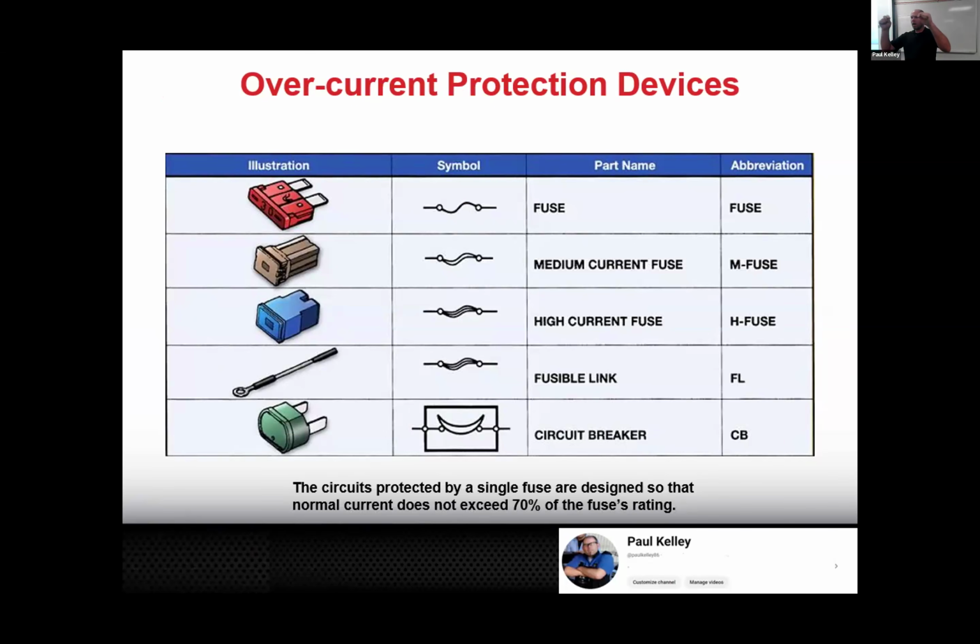You'll have regular wire, and then when they need to put a fuse in, but there's no room or something, they'll just cut a section of the wire out, and they'll put in a smaller size wire with a very gummy insulation. And if you think about it, if that's the smallest part of the wire, that's the part that would fail. So they're basically purposely letting the smallest section of the wire burn up.